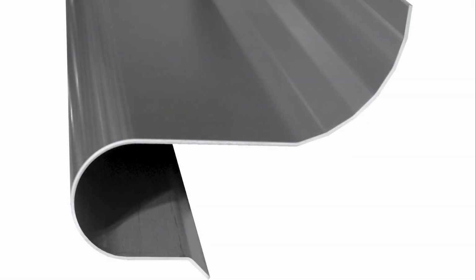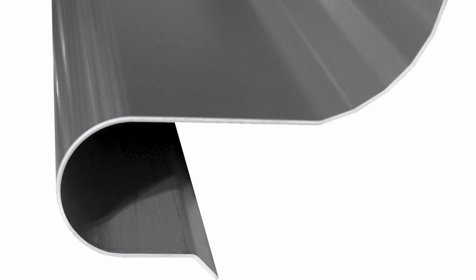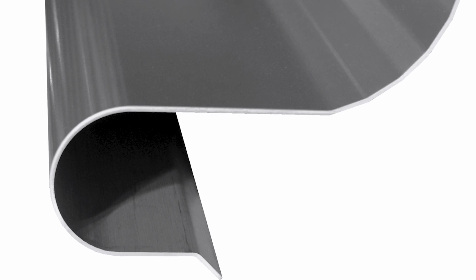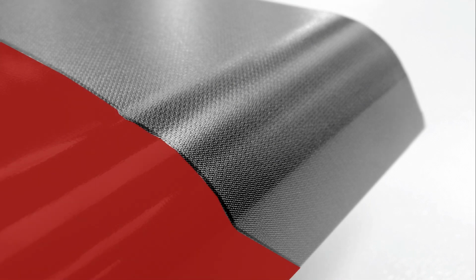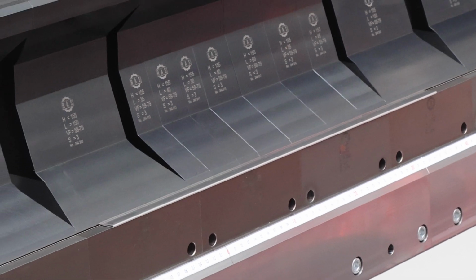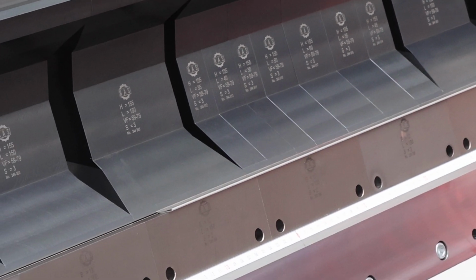Using small step lengths, like what can be seen on the part on the left, create radii whereby the transition from one bend to the next are not optically noticeable. Should the radius be needed for a purely functional purpose, larger step lengths can be used as seen on the right. Even pre-coated sheets can be formed in this way, with appealing radii. When the folding beam is positioned to a larger angle, the bending radii become smaller.